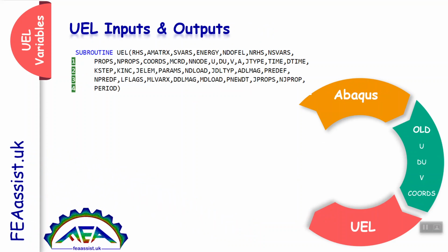We need to get these variables and define the interpolation matrix, interpolation function, and the element's force matrix, variables, and return these new variables back to Abaqus.